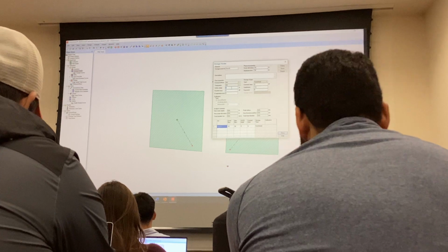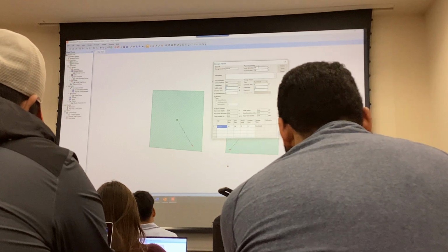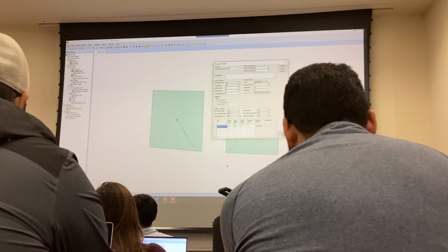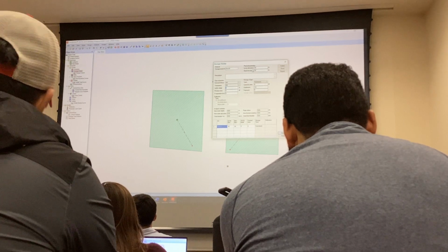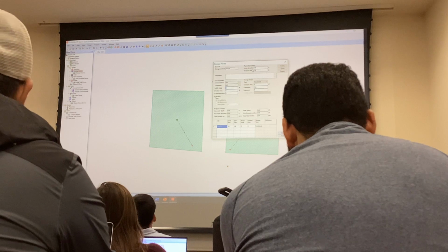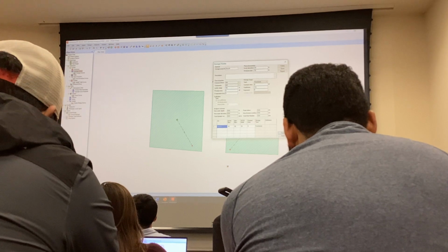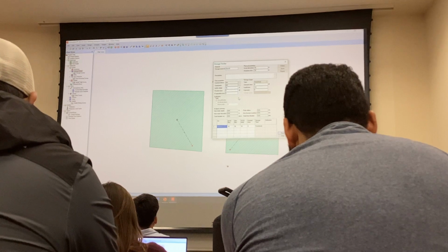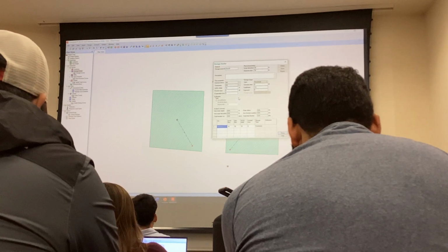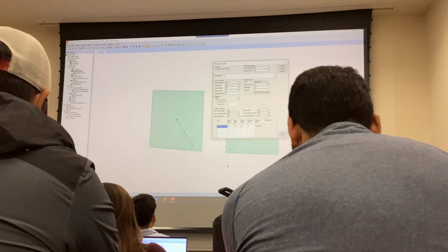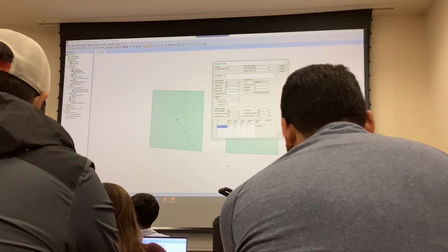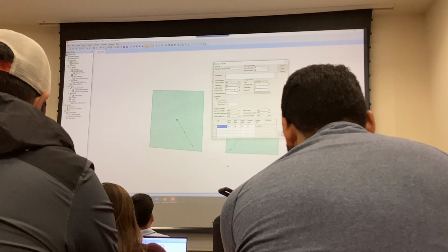So what that means is that since I have already fixed my inward elevation to 10, my minimum water surface elevation, even if it's dry, is 10, right? 10 means you don't have anything in there. So I'm going to put 10. The ponded area, sometimes when you design a detention basin, you can put a ponded area. I'm not going to include that here, unless you want to handle the water quality.